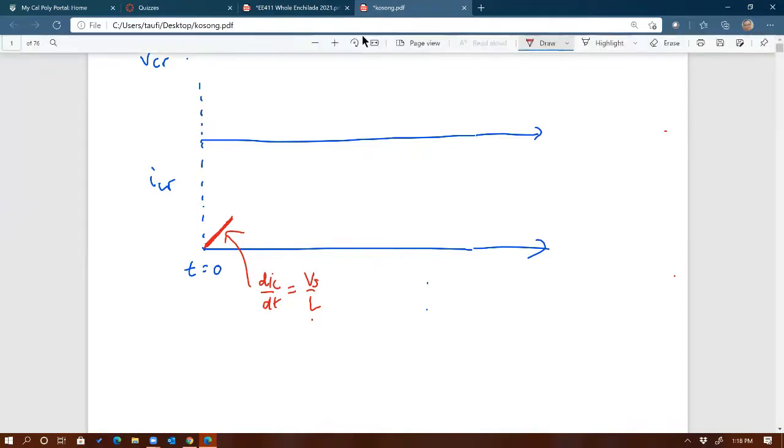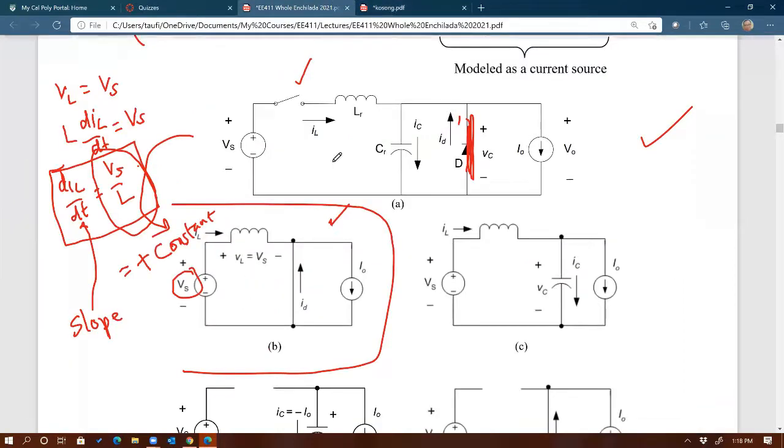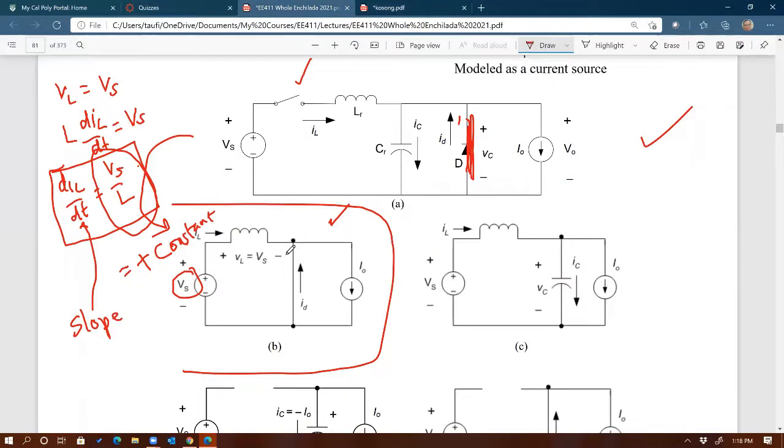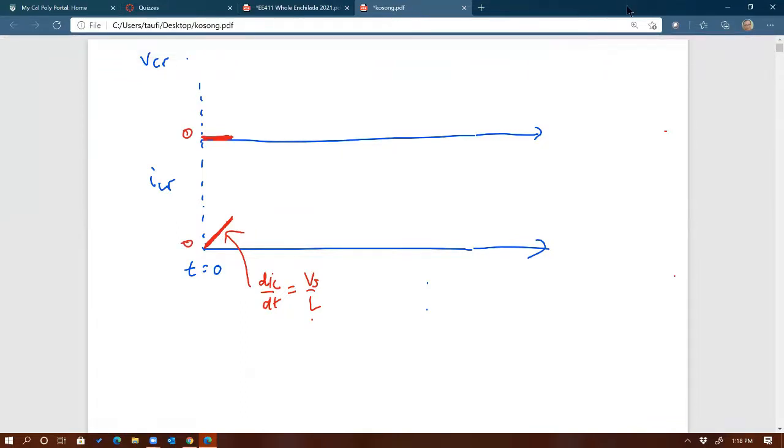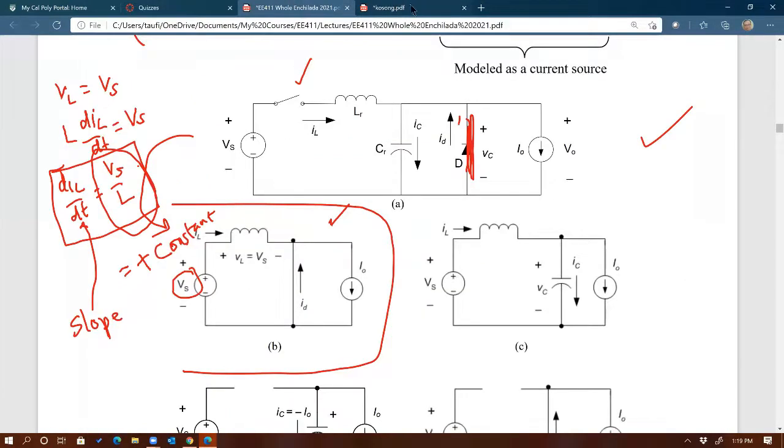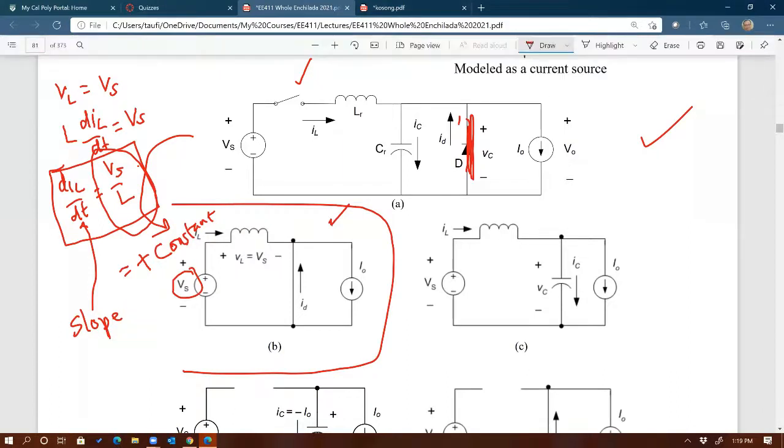All right. What about the capacitor voltage? That should be easy. What is the voltage across this cap? Imagine there's a cap across it. That should be 0, because it's right across the short. So if I were to draw the capacitor voltage, that's going to be 0. Any question on that? No? All right. Please interrupt me anytime you see things that are not making sense.